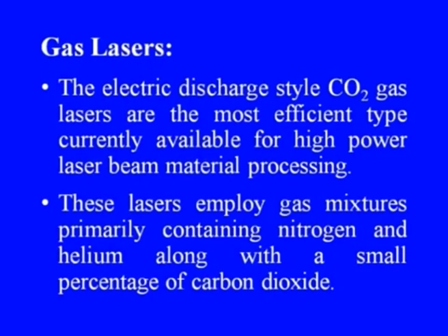Now, let us talk about the gas lasers, which are widely used in laser beam welding. As we have already indicated, carbon dioxide is the most popular gas laser. The electric discharge style of carbon dioxide gas lasers is the most efficient type currently available for high power laser beam material processing. These lasers employ gas mixtures primarily containing nitrogen and helium along with a small percentage of carbon dioxide.